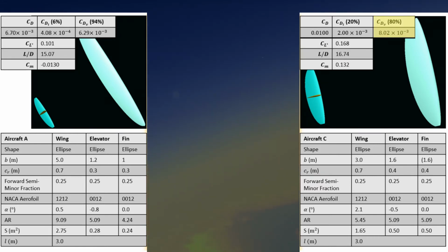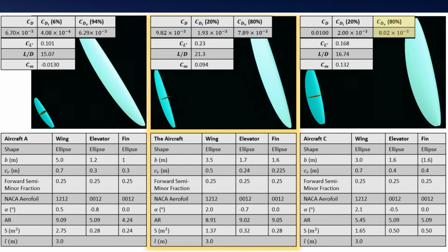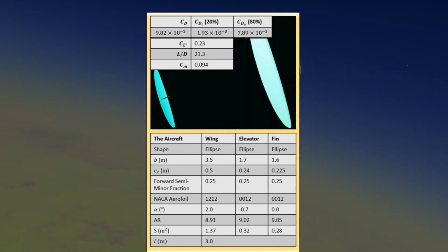Recall that we need a smaller area to reduce the more prominent viscous drag seen on Titan. We can then combine the benefits of the high aspect ratio with the low area to produce a more efficient aircraft. Recall that the speed the aircraft is designed for was based on a simple range and time estimate.